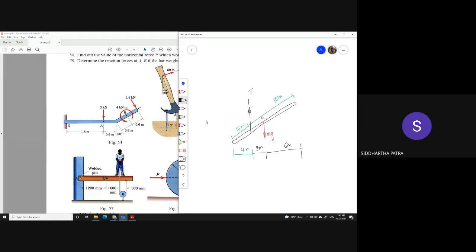Now this point is called A and this point is called B. See, dimensions must be there properly in the free body diagram. Now, the simple reason I would not consider the frictional forces: if nothing is mentioned, I'll mention that I'm assuming the walls to be smooth. If no comment has been made regarding the smoothness or the roughness of the surfaces, I'll simply assume them to be smooth, because with only 3 equations I can solve for 3 unknowns, and these are my 3 unknowns.